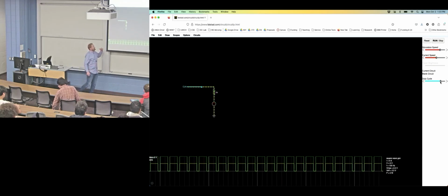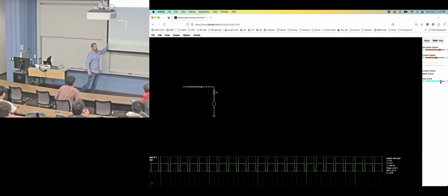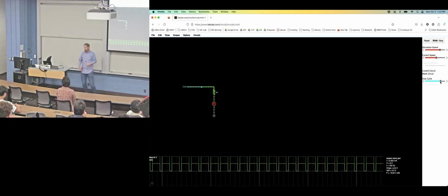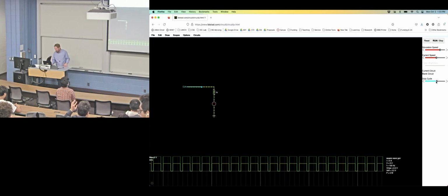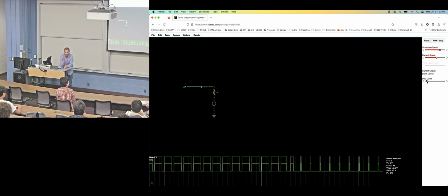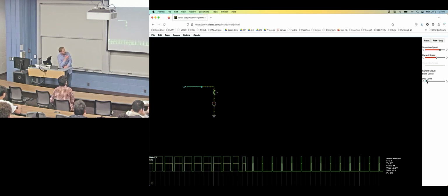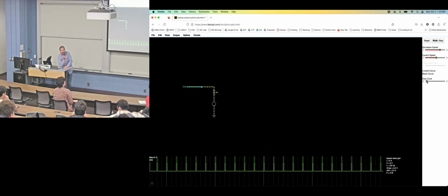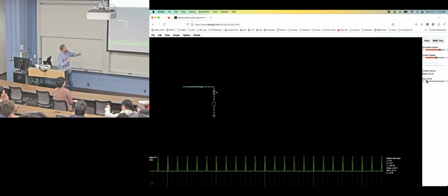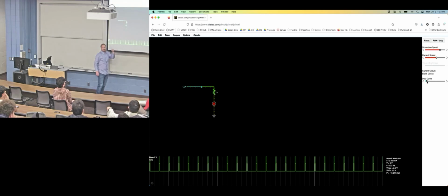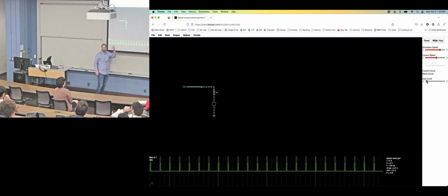Yeah, you also control motors this way. If you want your motor going particularly fast, you'd send a high duty cycle. If you want your motor going slow, you'd ramp that duty cycle down. From your motor's perspective, it's just getting these little effective current pulses. And then you do it fast enough so that the momentum of the motor kind of evens it out, so it feels like it's getting less current over time. Of course, this example doesn't work for you because it's all slowed down. But when you look at an LED, your eye effectively time averages this over, say, a kilohertz, and you think it's dim when it's really turning off and on.